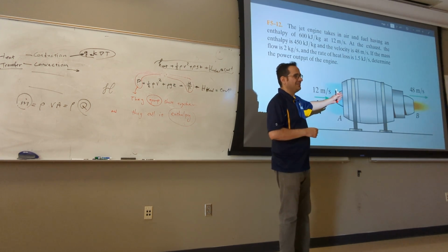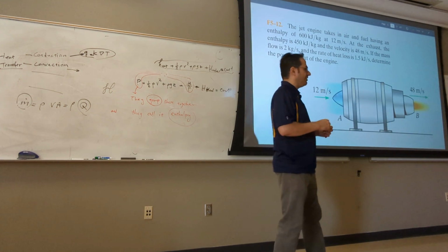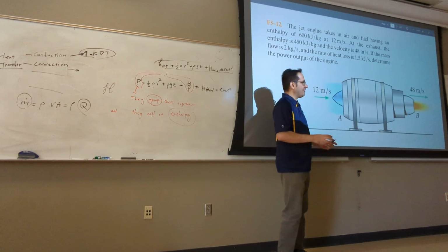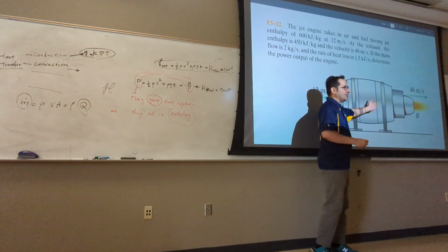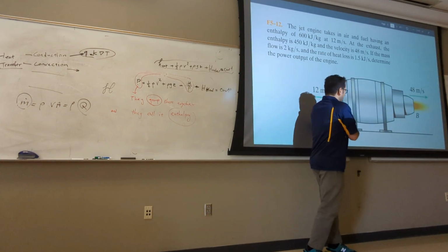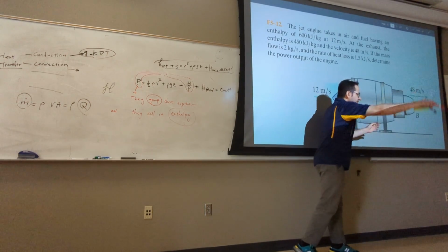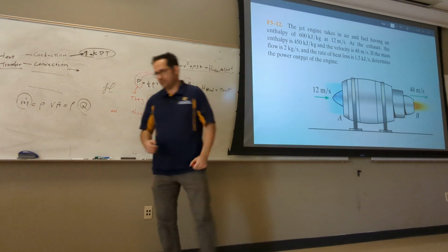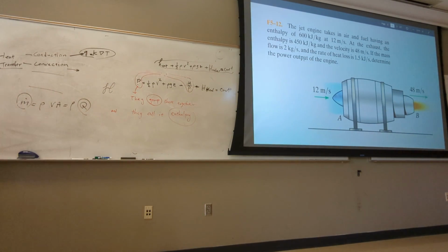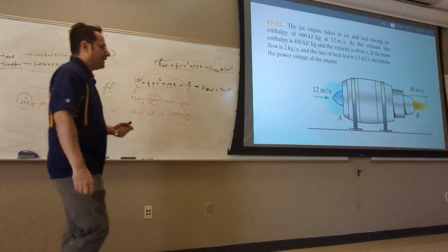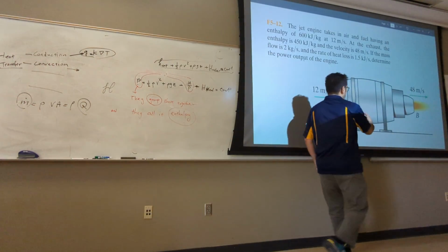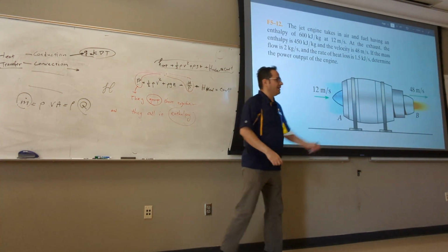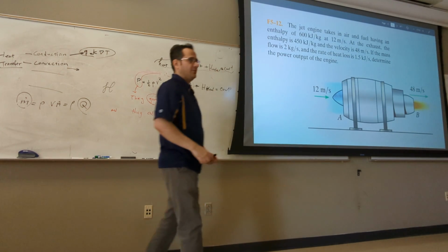In fact, we use different vocabulary like engine or thrust generator, but in fact, this is just a turbine. You apply this high enthalpy fluid to generate the work, to rotate that blade and generate the work, right? And there is a combustion there. This combustion, in fact, on top of all this, gives more head to that turbine. And that turbine sucks more air, so you can also generate thrust if you want to.